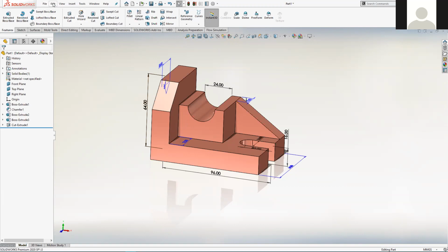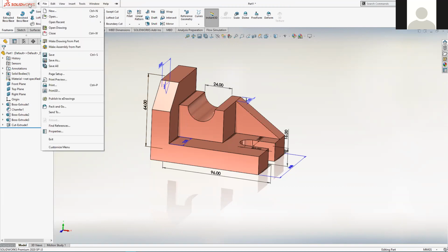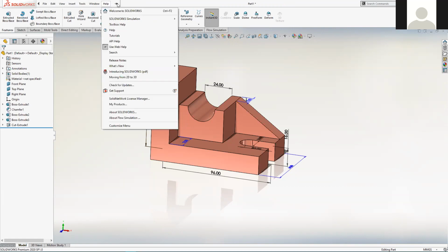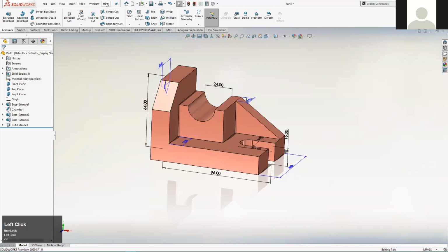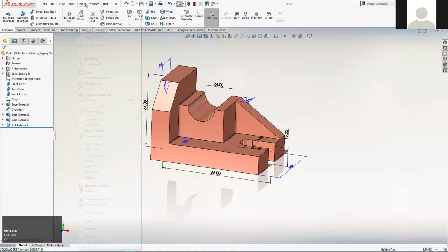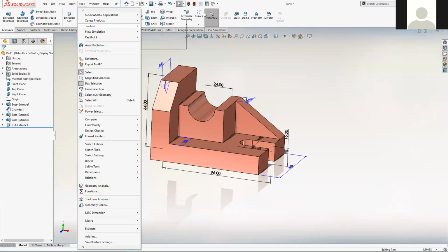And if you want your written menus visible all the time, just as we said last session, hover over that little black arrow at the side of the SolidWorks logo till it pops out, and then click on that pin at the end, and it will pin that menu permanently there, which allows you access to a lot more tools. It's just a more thorough set of menus.